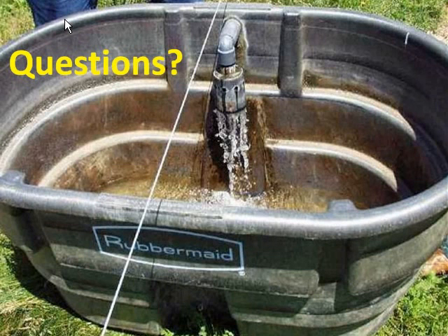So the best way to determine the flow rate is going to have a lot to do with the size of the pipe that you're using to collect your water and when that water is there. I mean, springs are one of those things. It's typically a drainage system, and a drainage system will provide water out the end based on the size of the drainage tile, as long as the water is there. But the big question is, what time of year? Is the water always there?